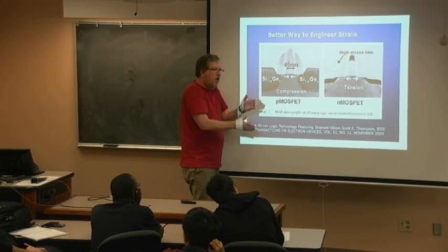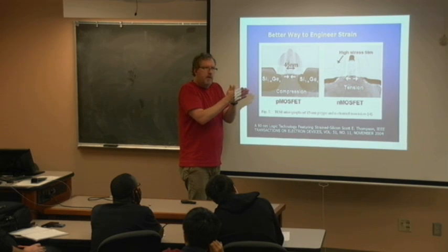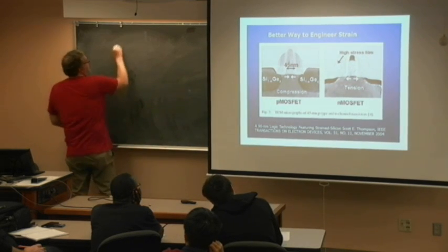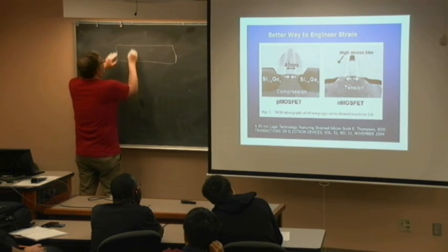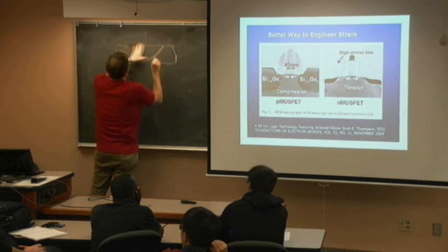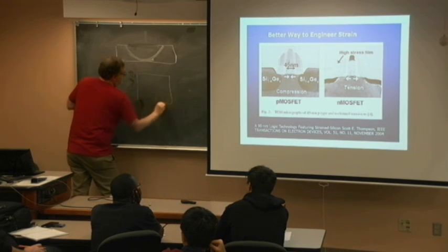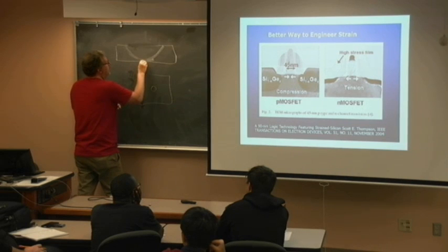I sliced it open and then I etched it to the point that it's electron thin. What you actually do is you start off with a disk and then you etch a crater. Eventually this pokes through, so this ends up being a hole in it. I'll punch a hole in this.